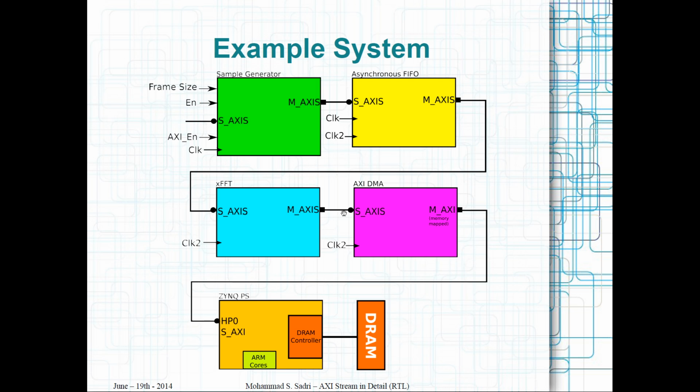Then these coefficients, just numbers, enter the module which is performing a very important task. It is called AXI DMA. The AXI DMA, as I will show you, is responsible for receiving your AXI stream data and then passing it through an AXI memory mapped interface to the ZYNQ PS. As I told you in a previous video, the AXI ports that we have on the ZYNQ PS are all AXI memory mapped ports. We don't have any AXI stream port on the ZYNQ PS.